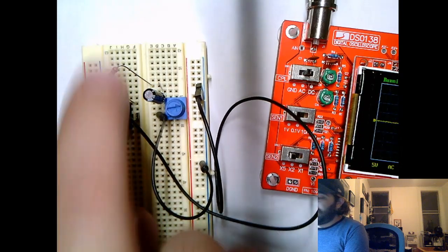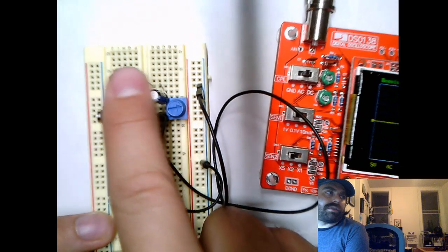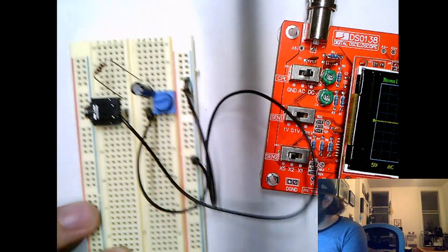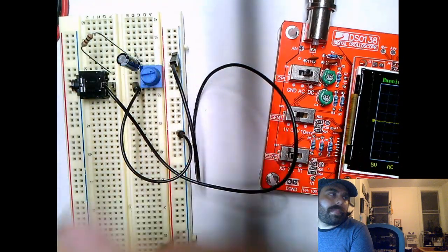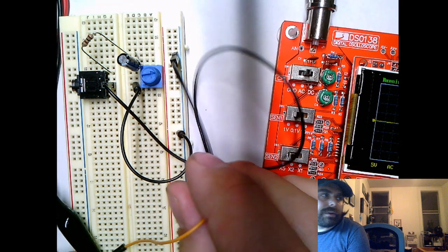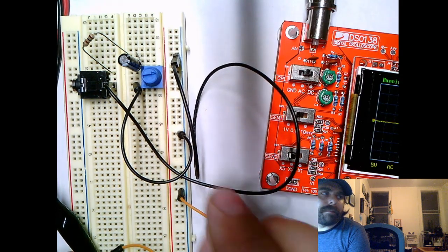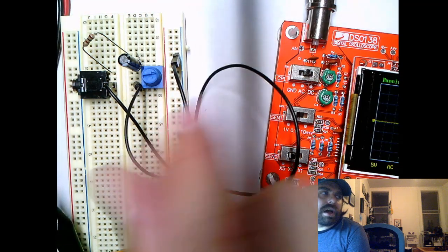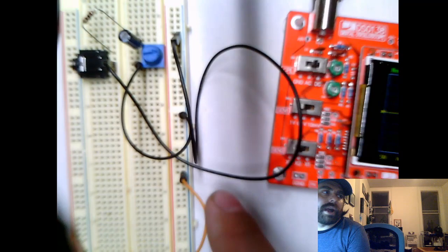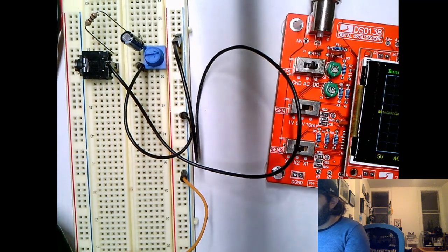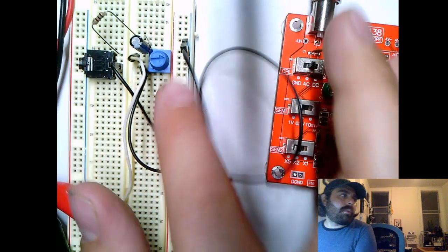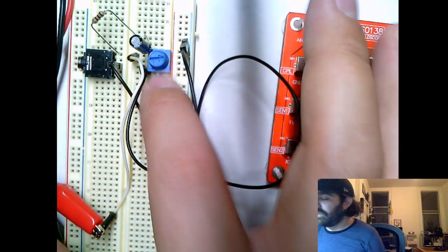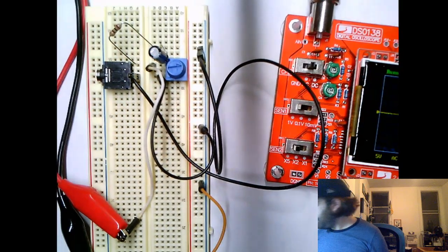The rest of my signal is going through my resistor, through the capacitor, and into the potentiometer. Now I'm going to get my two probes. The black probe I'm going to put into ground because it's always grounded to the other wires, right? So I have my probe, I have my potentiometer, I have my signal all grounded. First thing I'm going to do is take my red probe and I'm going to put it in the same row as the capacitor and the potentiometer. I want to make sure that I'm seeing the full signal. So we're not turning this just yet.